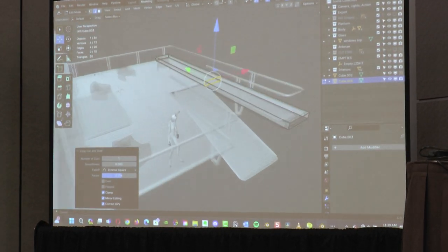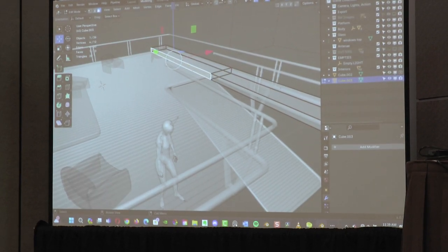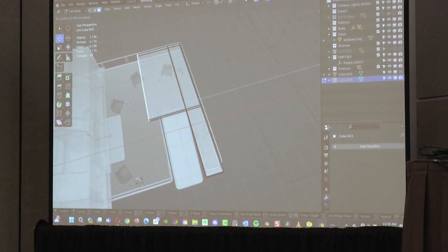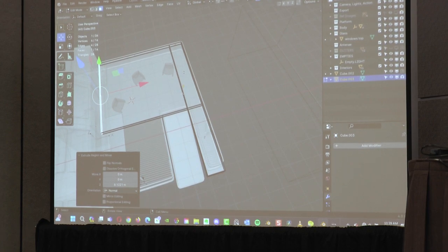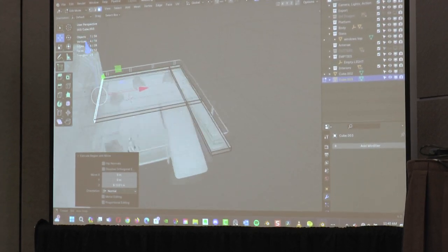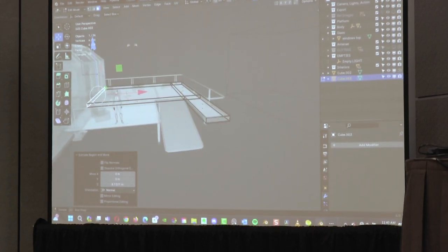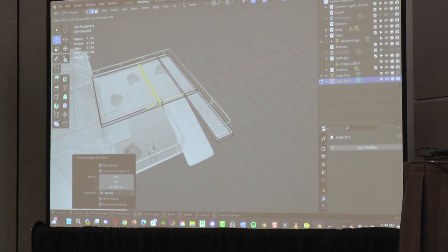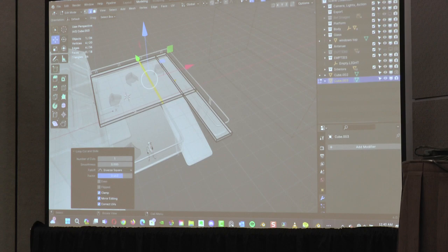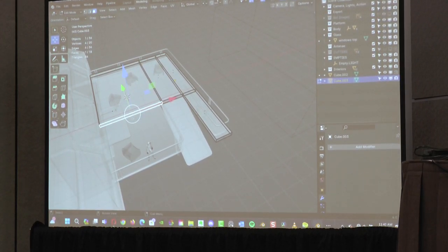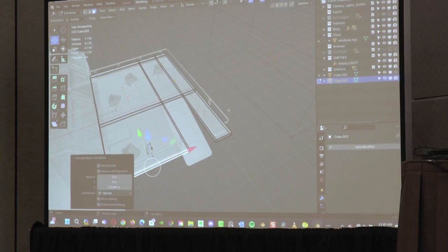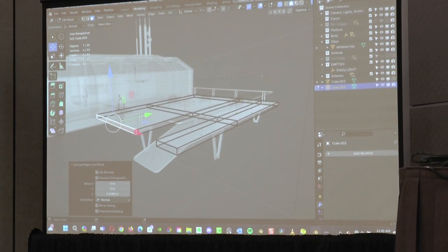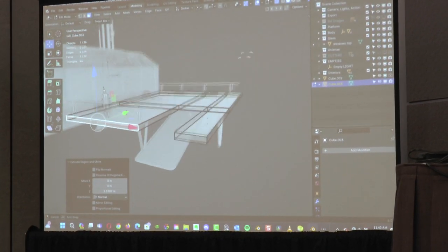I'm going to grab the face, okay. Grab that face there. And we're going to extrude it out. E for extrude. Extrude it out like that. Okay? We need another slice for this edge, right? Because I want this open, we want a force field around the entire piece. So Control R for slicing, left click and hold and put it right about there. That is good. Grab that face here. Okay? E key for extrude, and there's your force field. Is that making sense so far? Yes, no, maybe so? Okay, so that's your force field.